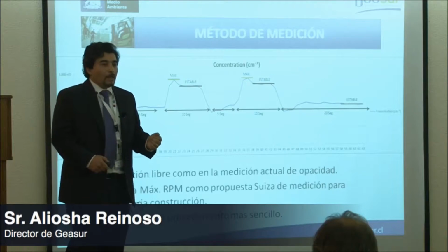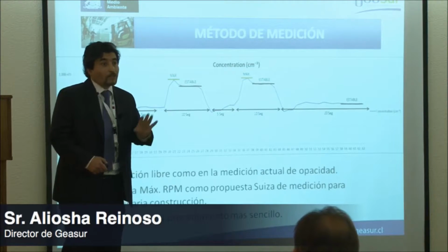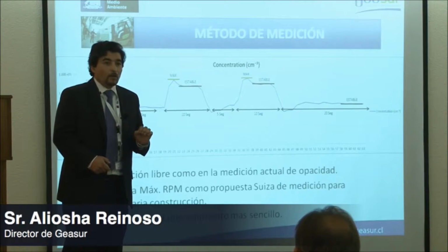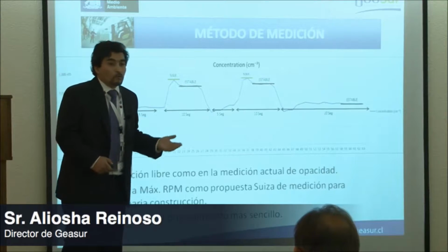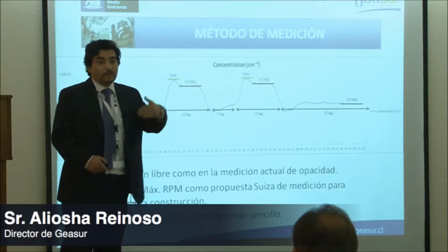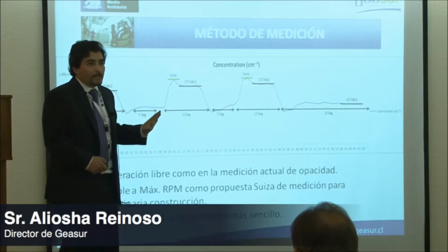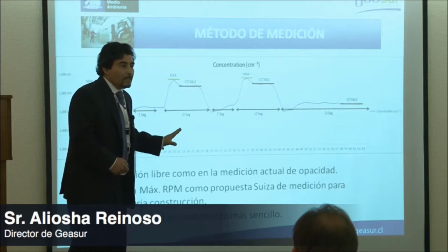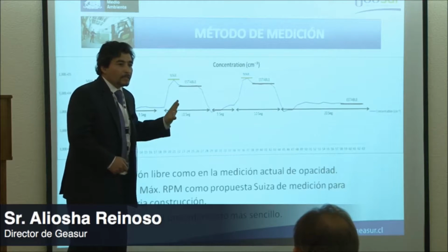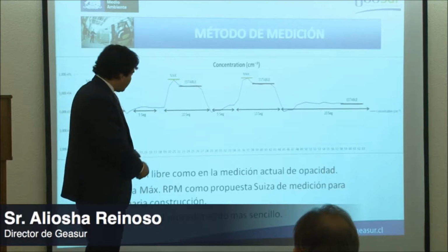Now, I have to tell you the story about this opacity regulation, and diesel emissions regulation in Santiago began with idling opacity. Obviously, it came to a point where every bus was measuring 0, and then we went to free acceleration. Well, as of now, the fundamental difference is that there's a sensibility to it that allows us to measure in idling, where we can detect the emissions in that condition.